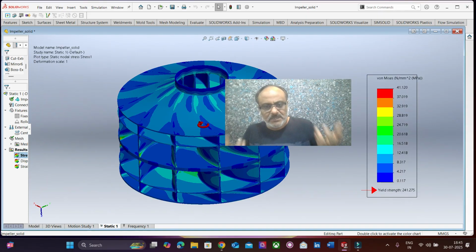Suspension will drain out some loads because it has a spring and a damper system, so many forces can be dampened out. The tire itself, being a non-linear material, can again dampen out some part of the forces. Apart from that, the major part of the impact that comes from potholes or speed breakers has a direct influence on the chassis.